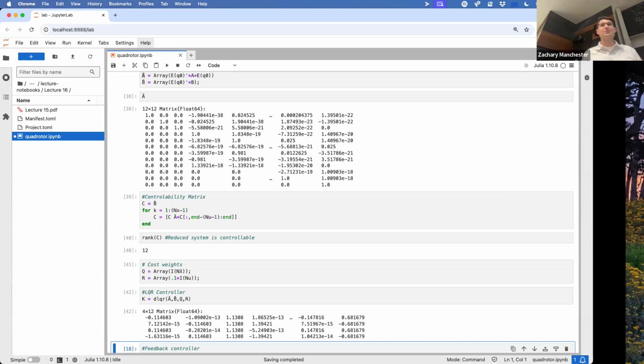You could invent one that was singular at 0. In fact, there is one that does. These are so-called shadow parameters for the modified Rodriguez parameters. The deal there is that it has a singularity at 360, which is equivalent to the identity, right? So there's a so-called shadow set that flips it around and has the singularity at 0.